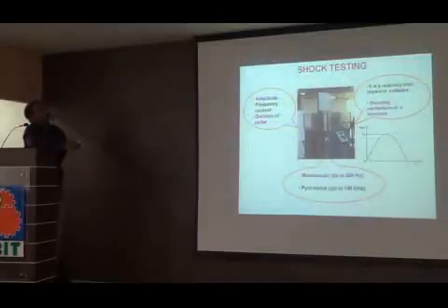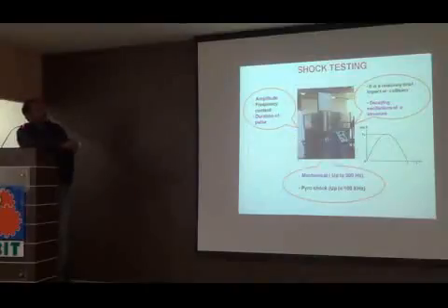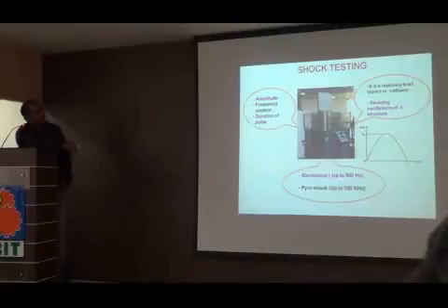So what we do is we use some kind of shock testing machines. The characteristics of this shock I have listed here. It can be amplitude, frequency, and duration of pulse. So it is a relatively brief impact. A typical curve is shown here. See, it is a half-sine shock. One axis is the acceleration, one is the time.